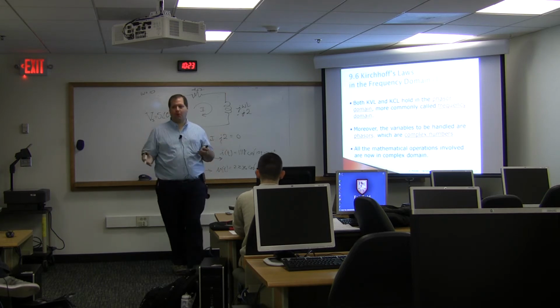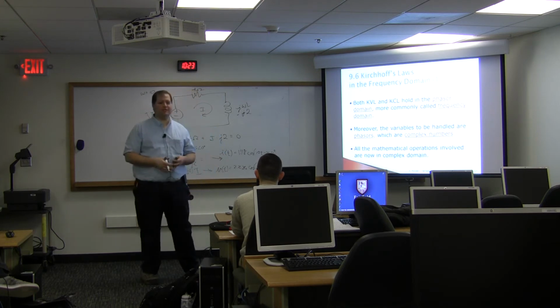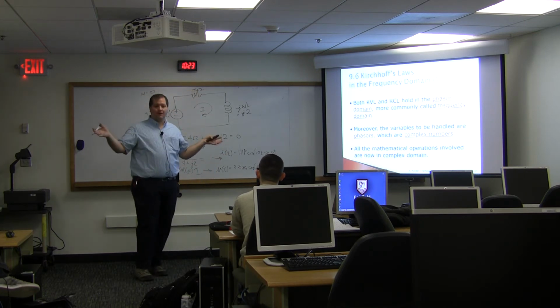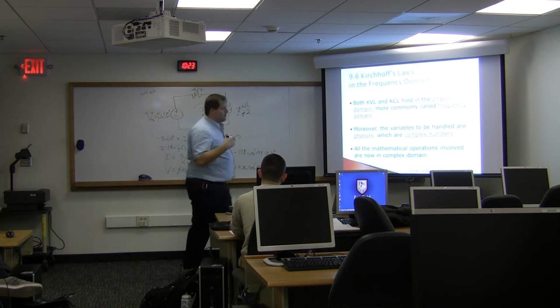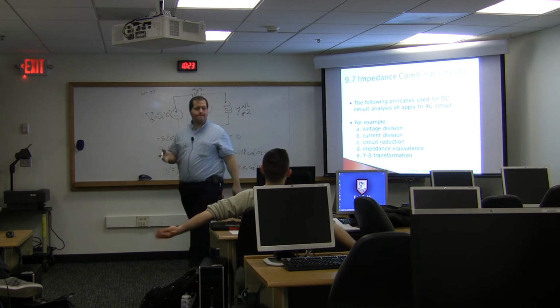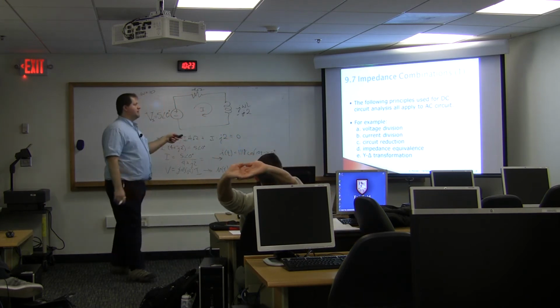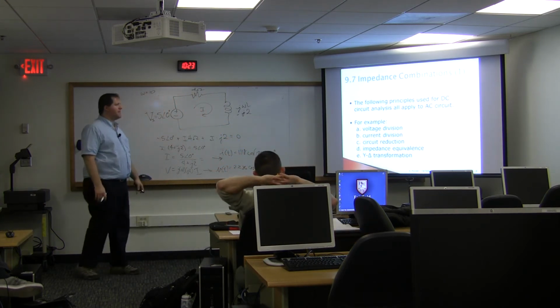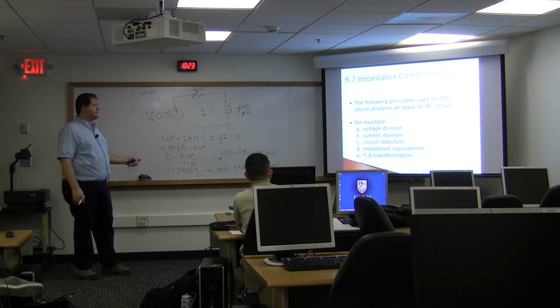MATLAB can do all of those polar to rectangular conversions for you. You can type them all in together, and it won't care. It will just calculate them, right? So MATLAB is your friend, even more so than it was before, right? We can do, as I mentioned as well, all of the impedance combinations that we did in DC analysis.